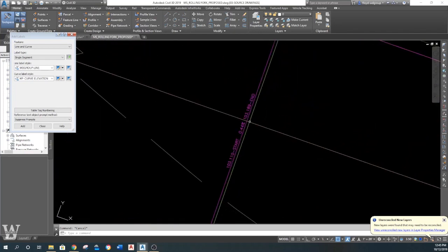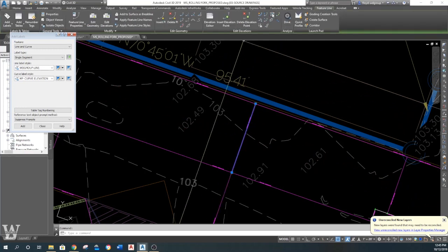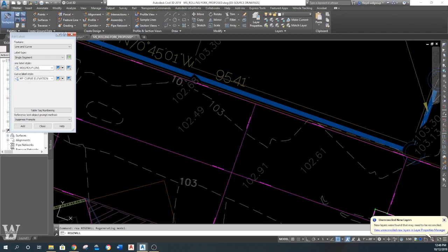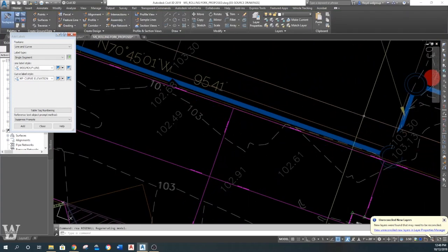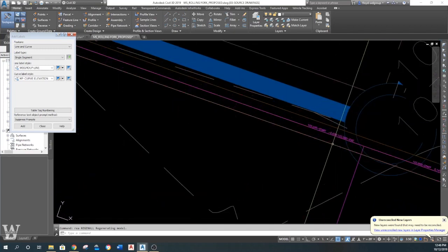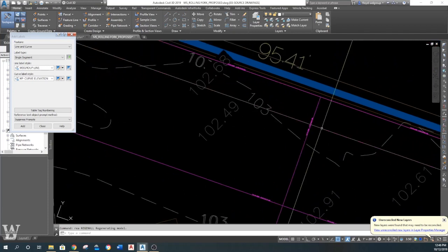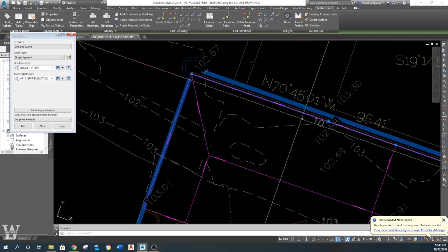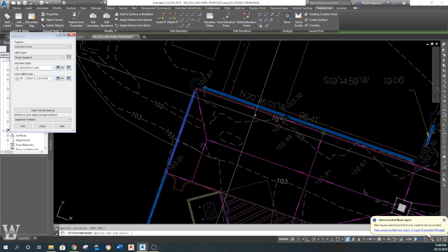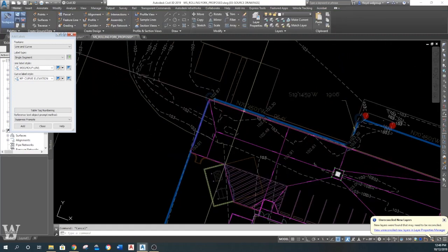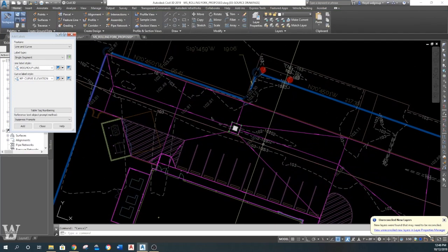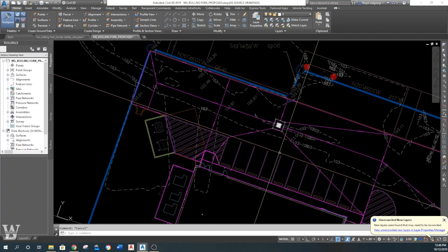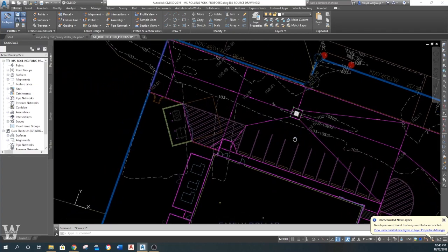All right, so I'm a little bit flat right there. So I'm going to take that and grade 0.75. And that's still at 103.2, so I'm still close to that old slab height for the existing grade, for the bottom of the curb. And it gave me a little slope that way, and it's still kind of flat that way. What I'm going to do is grade from here to here straight across. It's pretty flat, so hopefully I've put some slopes into everything right there. Okay, by putting that pipe in. I didn't want to put that inlet in, but I wound up putting it in.